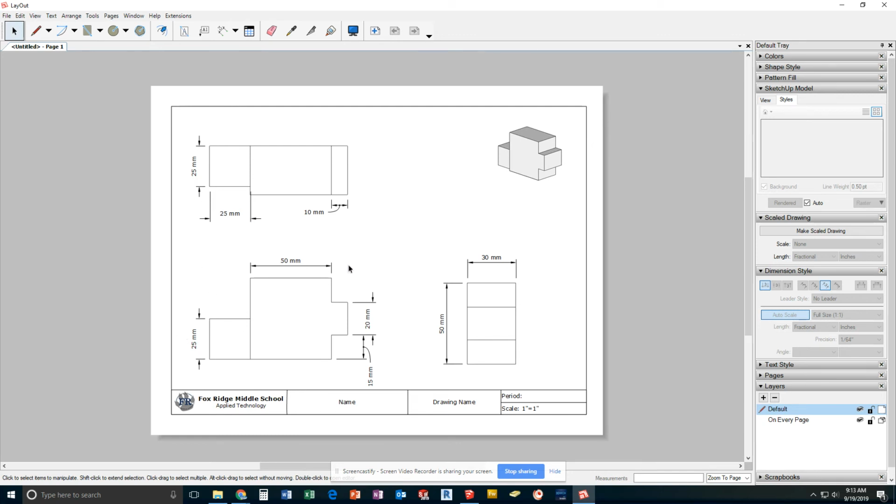So while we prefer to put the dimensions in between, sometimes we have to go to the outside. You should space your views so that you can put the dimensions towards the inside. If there's a feature you absolutely have to dimension from the outside, you can do so. But dimensioning this out here where there would have been another option, that would lose you points. For example, if I moved my right side in too close to the front and decided I'll put the 50 millimeters on the outside, that would be unnecessary because I should be able to scoot my view over and put it in there so it's between the views. Because again, this height also corresponds to this, which is why we lined everything up.